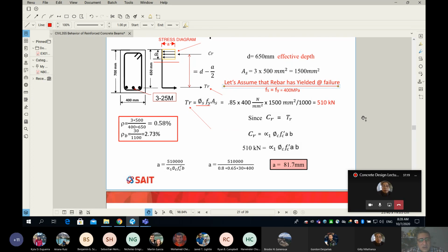Okay? So in my class, you will see, I will do lots of assumptions. You will start seeing them probably next class when we start the design. But you will see, once we make those assumptions, they will make our life super easy mathematically. But at some point I will have to come back and verify my check. So it's okay right now to assume that my rebar has yielded, given that later on, before I finalize my conclusion, I need to make sure that this was true. I'm going to show you how.